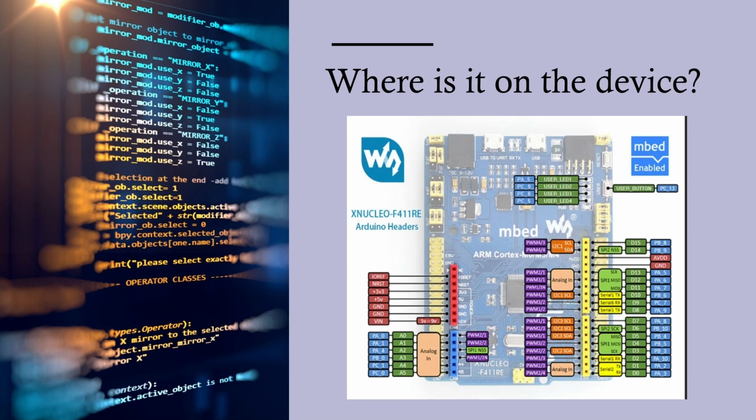You see the peach-colored analog in, and there's a line that says A1 and PA1. It can be A1 or PA1, but you can't use both. A2 or PA2, they're both connected the same. A3. I like to use A3, A4, A6; that kind of helps me out.